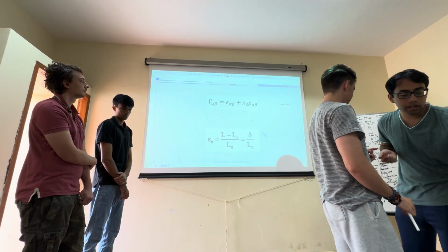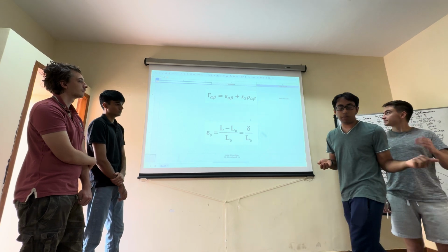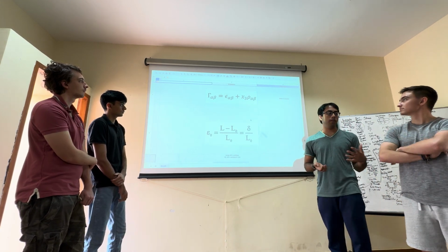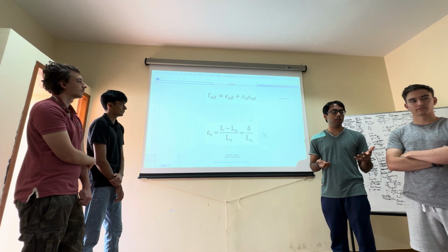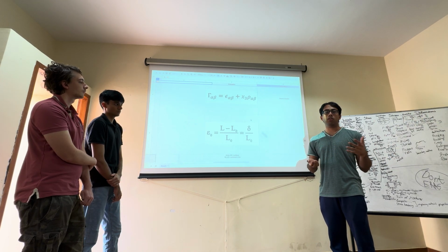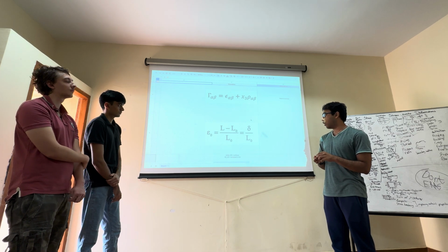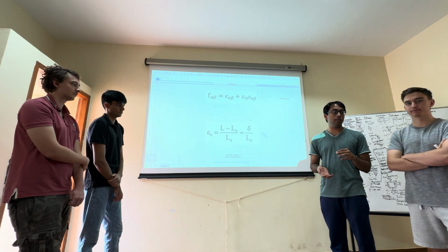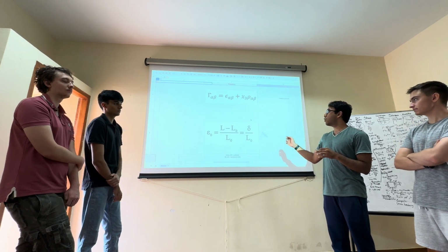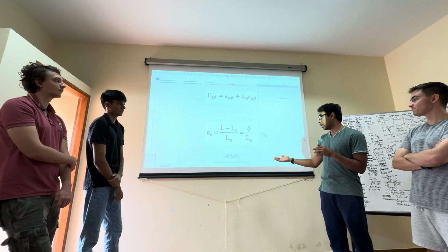One of the equations that we didn't include yesterday was from the Kirchhoff-Love hypothesis that you mentioned in your email. We wanted to differentiate the units here. Previously we mentioned that strain could be unitless, but if we do dimensional reduction, the units do change. In Kirchhoff-Love's hypothesis, for 2D and 1D, it can be both unitless and have the units of 1 over m. Specifically, epsilon is unitless, and rho is 1 over m.